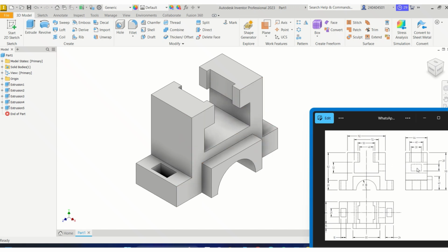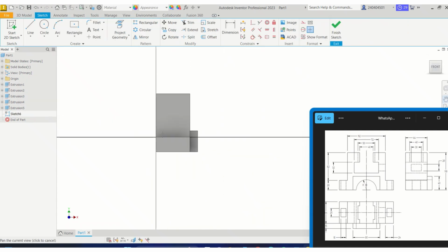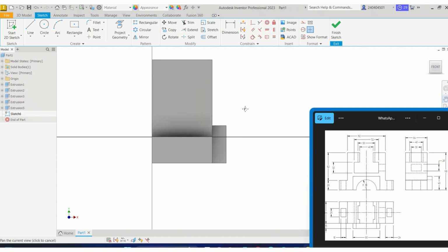So what is left is this from the other side. Okay, the side view, so it should be here. So I'm going to click on this. Okay, sketch. That has been given to be 20 by 30, 20 by 30. I need to be at the center, the same center as this, so let me look at the center line that passes through this.